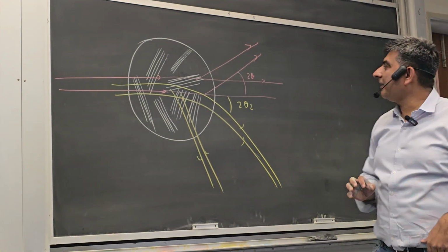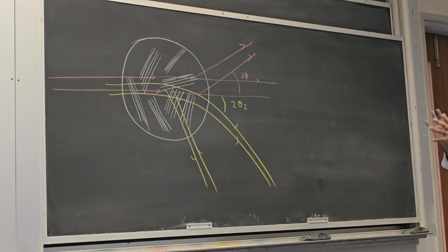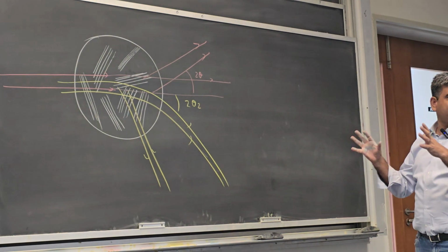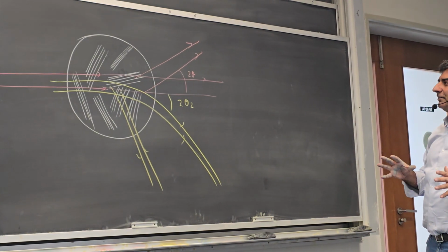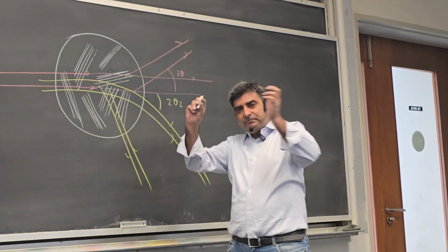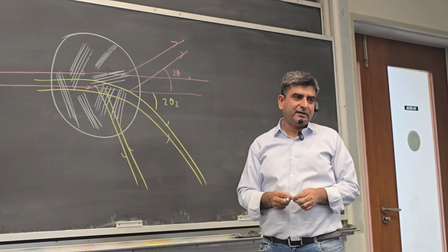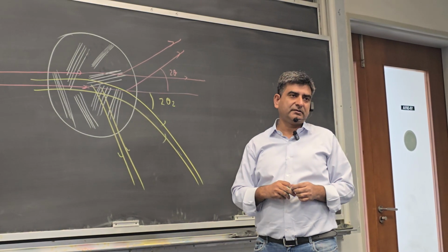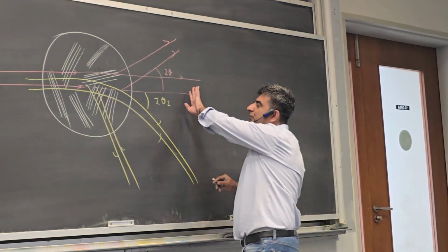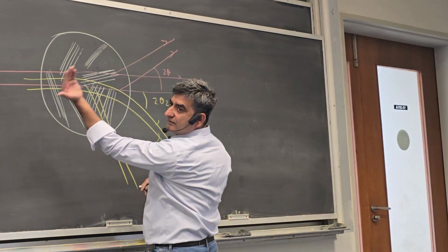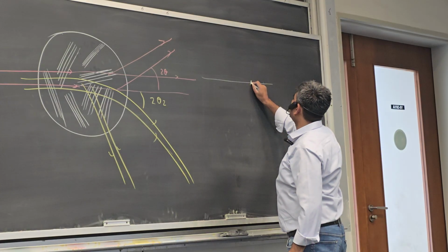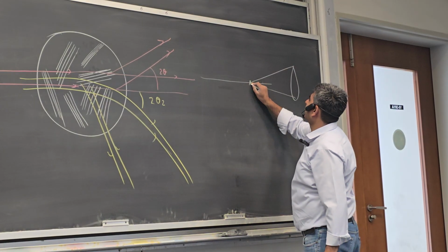All right, so if I were to convert this into a practical apparatus, a practical machine that can look at the directions of these scattered X-rays, what would that look like? One possibility is I have some kind of film that is sensitive to X-rays, and I wrap it around the specimen. So suppose I put a film like this in 3D. What's really happening is that if this is my sample, I am getting cones of scattered radiation.